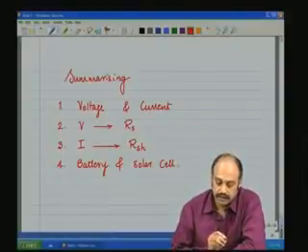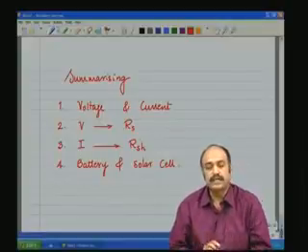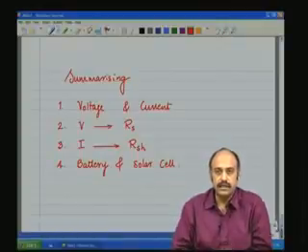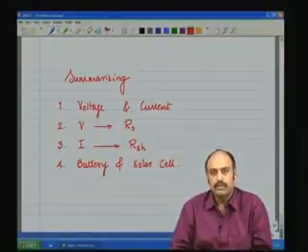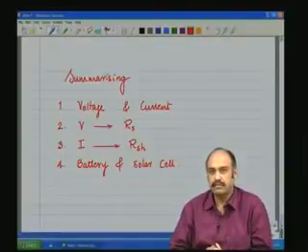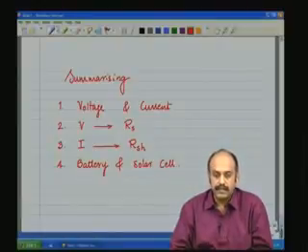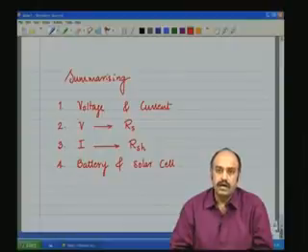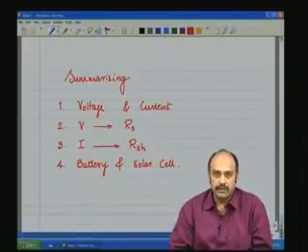You should keep in mind that the internal resistance Rs and the R shunt that we have seen in today's discussion need not be purely resistive. It could also be inductive, or a combination of resistive, inductive and capacitive. That is, it could be an equivalent series impedance instead of just equivalent series resistance in the case of the voltage source, or an equivalent shunt impedance instead of a simple equivalent shunt resistance in the case of the current source.